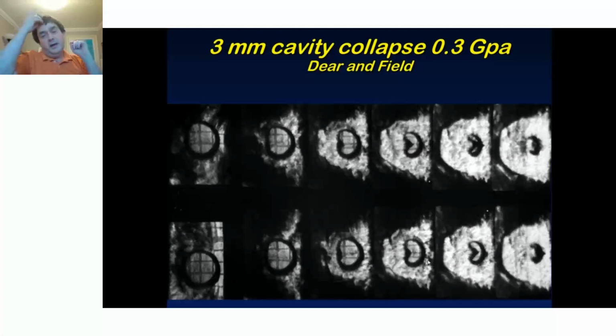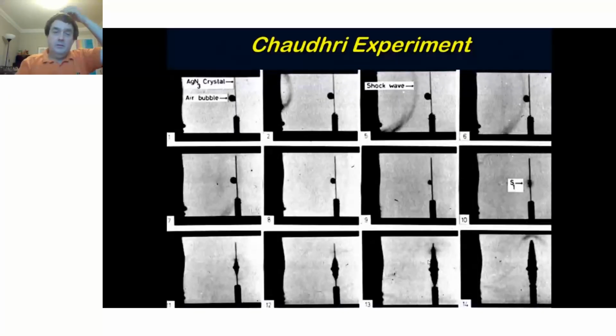It produces high pressures, high temperatures, and you've also probably got some heating of the gas as well, so it can entrain some hot gas. But the main thing is the shock of the impact on that downstream side of the bubble. Here is an example of what happens.